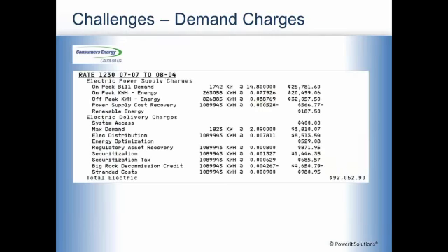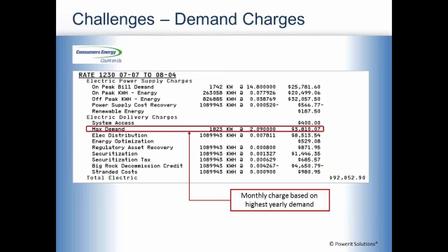Typical utility bill that I would see here in Michigan, you can see there's multiple line items on it. The kWh is the actual energy charge, which is based upon total number of kilowatt hours. The kW would be the charge that you would be paying for the particular period. You can see here the maximum demand charge.